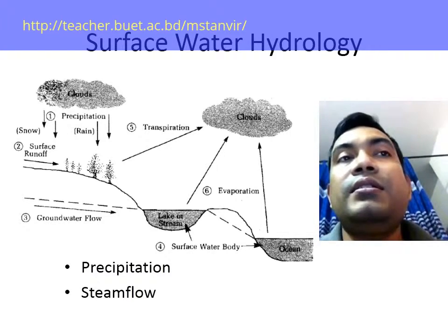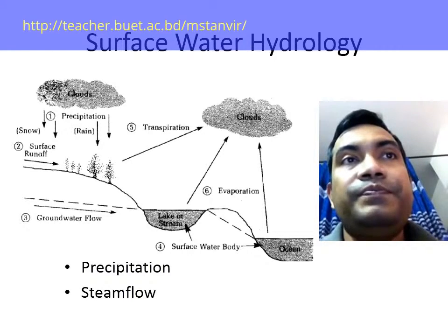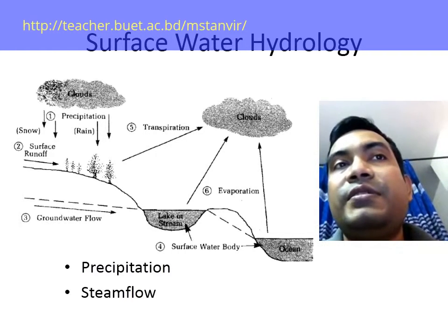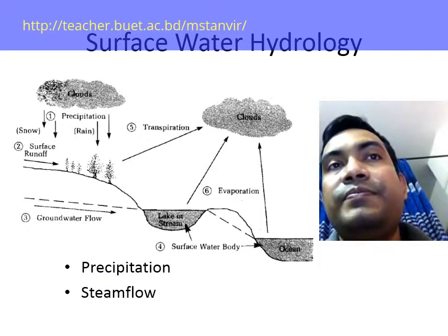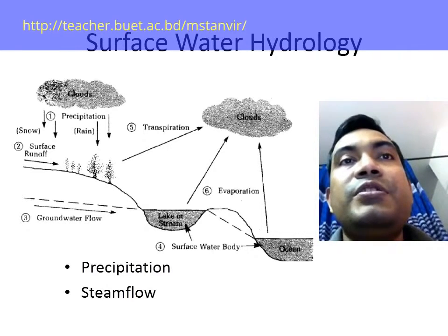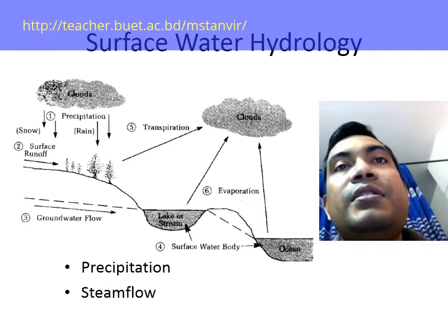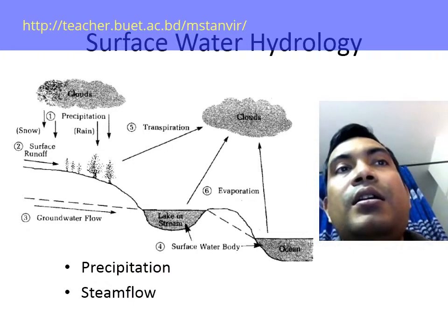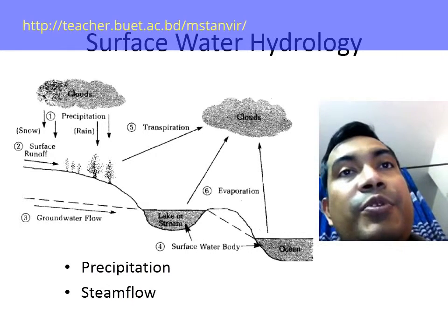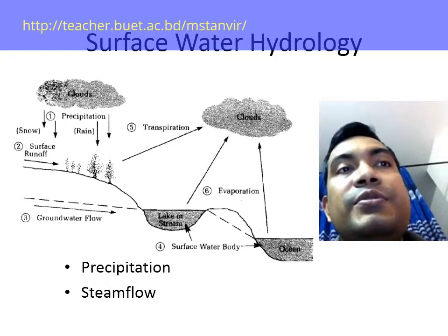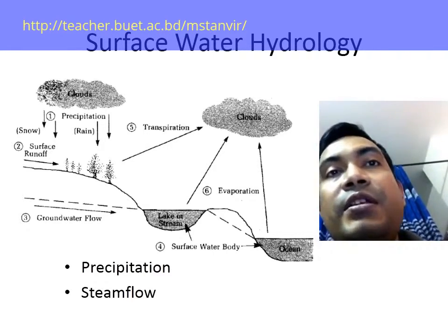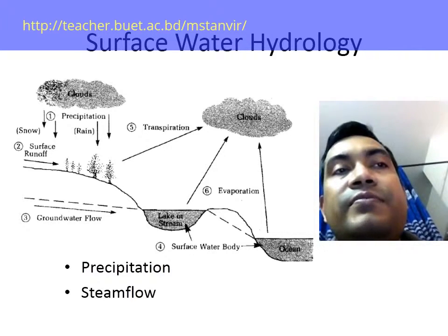If the soil is dry and porous, the precipitation may infiltrate, or maybe it only wets the surface, which is called interception, or the precipitation may be trapped in small depressions. The four factors, evaporation, infiltration, interception, and lastly trapping, that reduce the amount of direct runoff are called abstraction.